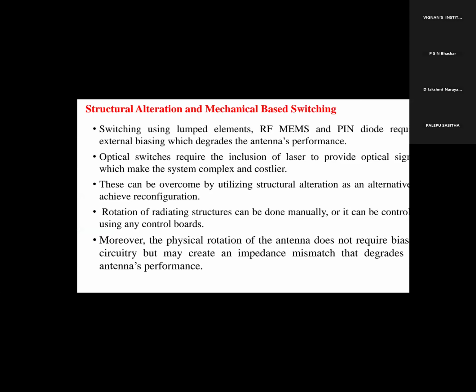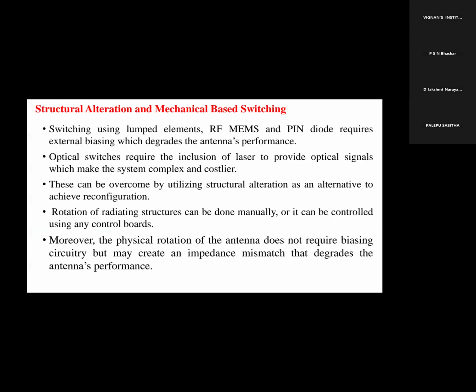Switching using lumped elements, RF MEMS and photodiodes requires external biasing, which degrades the antenna performance. Optical switches require incorporation of a laser to provide the optical signal, which makes the system complex and also costlier. These can be overcome by utilizing structural alteration as an alternative to achieve reconfiguration.